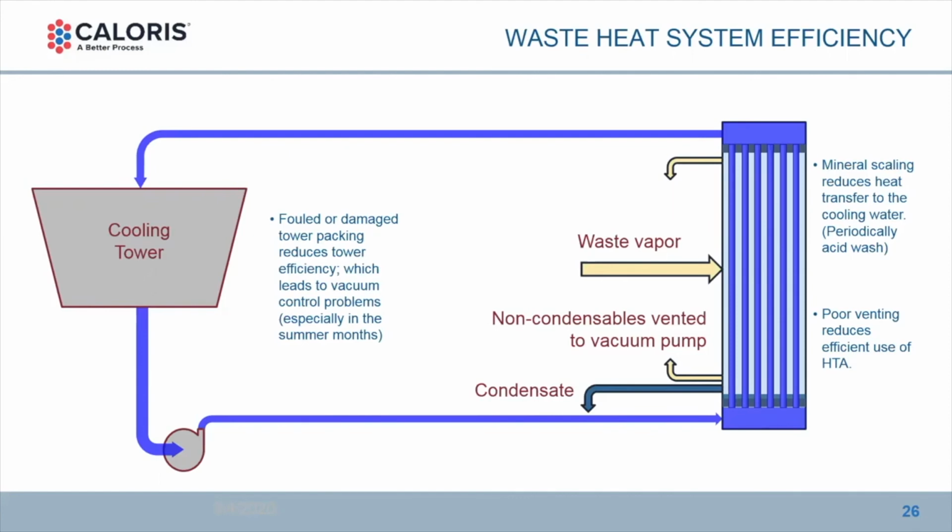And then, of course, the cooling tower. If you've got fouled or damaged packing, you're just recirculating hot water and not giving it an opportunity to do its job as designed.